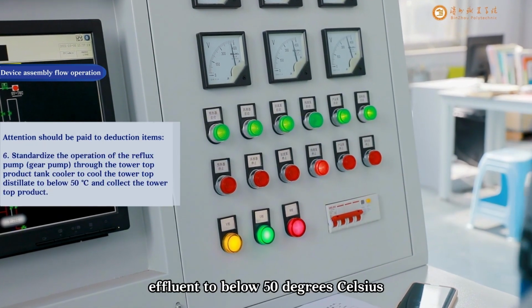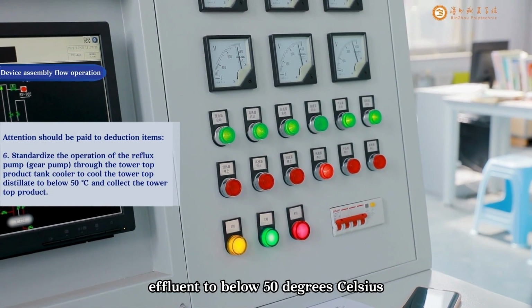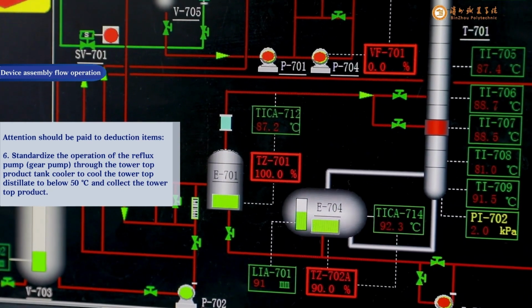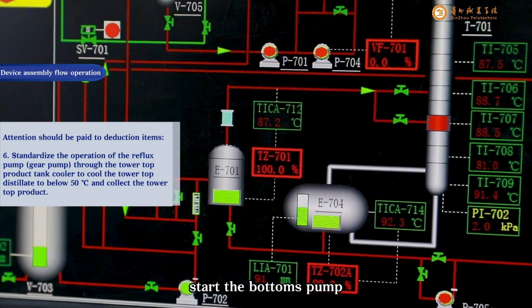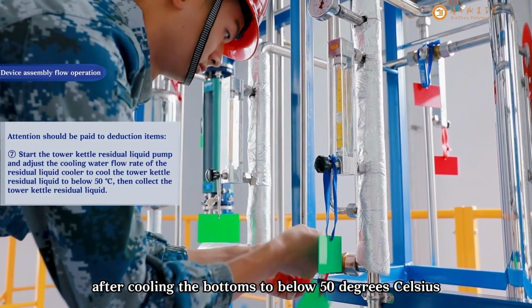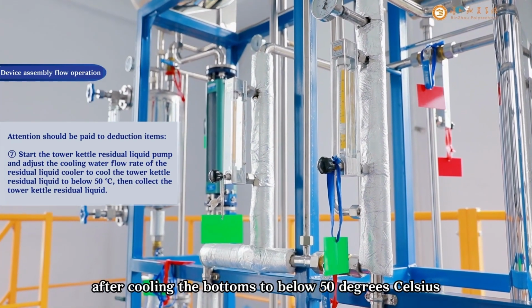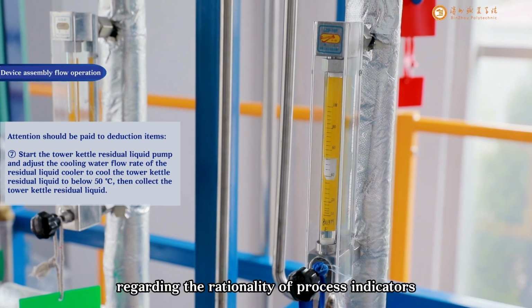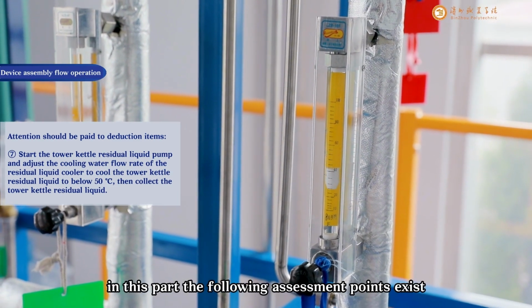Cool the overhead effluent to below 50 degrees Celsius through the overhead product cooler, and collect the overhead product. 7. Start the bottoms pump and adjust the cooling water flow rate for the bottoms cooler. After cooling the bottoms to below 50 degrees Celsius, collect the bottoms. Regarding the rationality of process indicators in this part, the following assessment points exist.